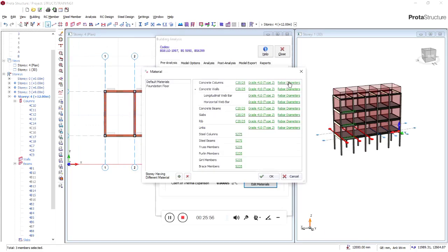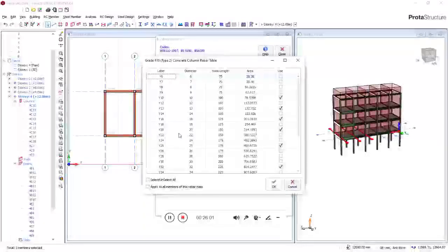And the rebar for concrete column. Now this is a 3-story building, so you are going to be having reinforcement on the ground floor, and this is the structure we are looking at now. When we run the analysis, you will see one or two things there. Because this 225 by 225 is a 3-story building and is a block of stores where they will be putting the goods, this 225 on this ground floor will not pass. But nevertheless, let's run the analysis first.